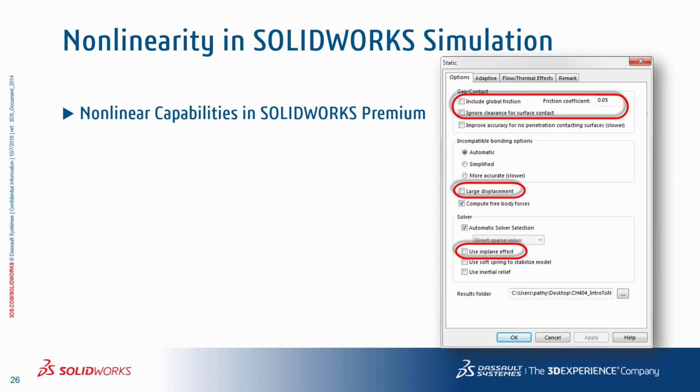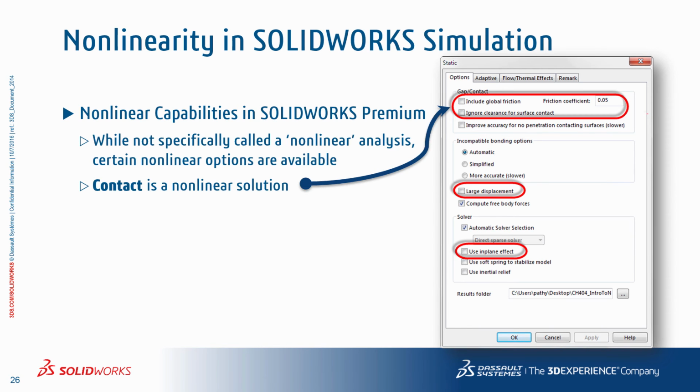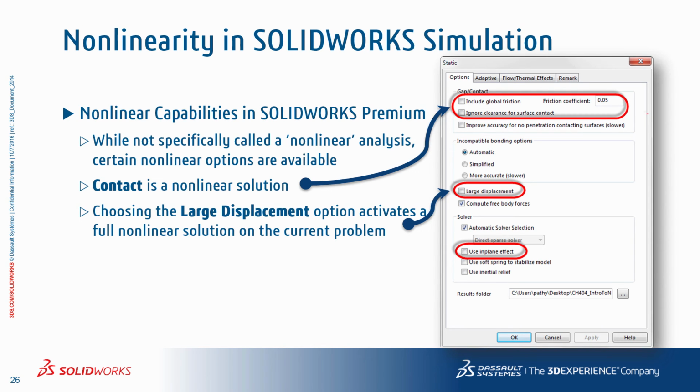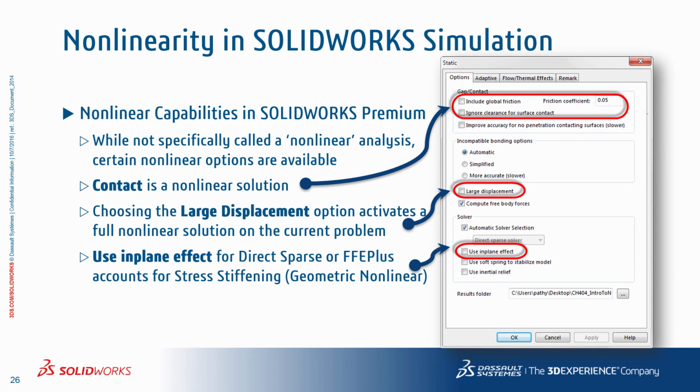Let's start with SOLIDWORKS Premium. Contact analysis, or the capture of multi-geometry interaction, is a nonlinear effect falling into the boundary nonlinear category. Friction can also be included in the contact definition at the linear static analysis level. Now, there are also tools to include geometric nonlinearity, which is available by choosing the large displacement option as shown. Choosing the in-plane effect also turns on a nonlinear effect on the solution.